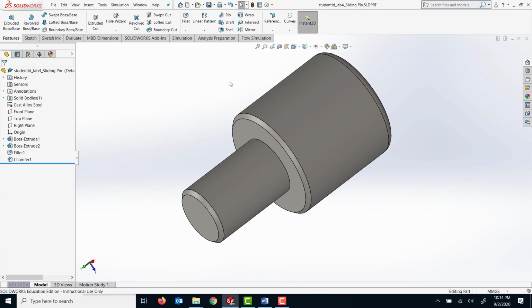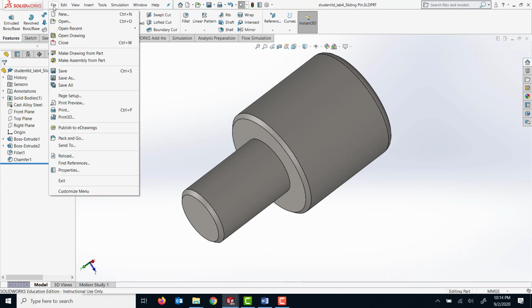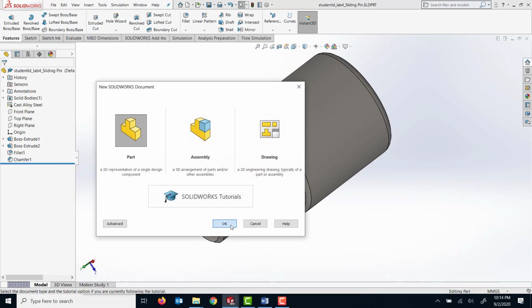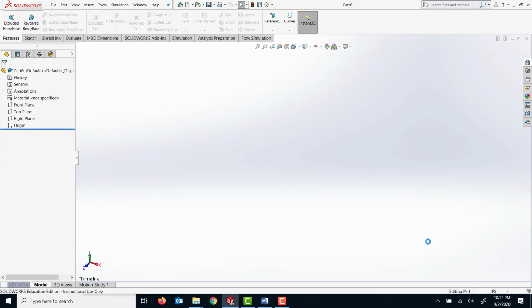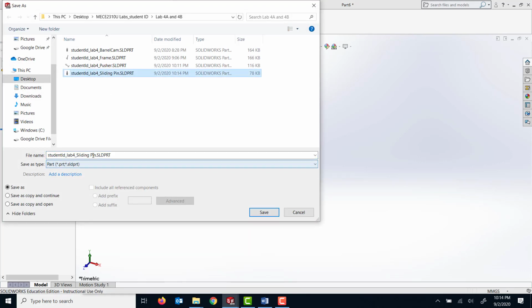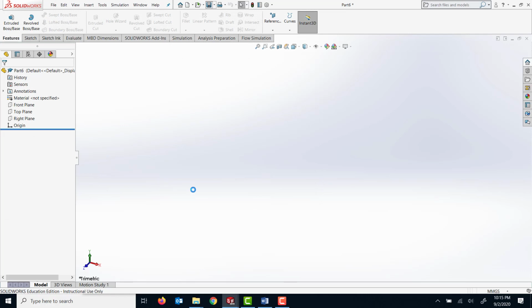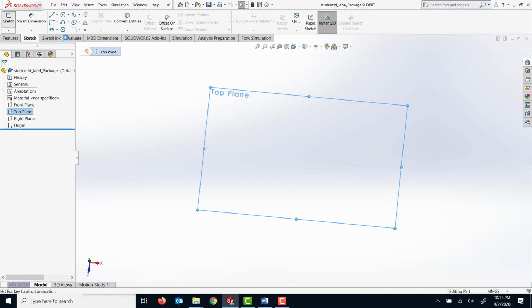Now the last part that needs to be created is simply the packages that will be transferred over. So I'm gonna create those parts now. Simply gonna go open a new part file. I'm gonna set the units as mmgs, and I'm gonna save this file as, I'm gonna name it packg. Gonna save this file.